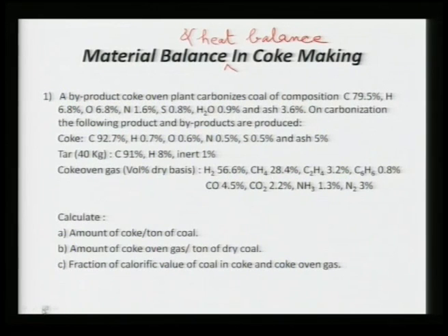The coke oven gas, you see the composition of the coke oven gas. If you look very seriously over here, you will find that hydrogen and methane are in the main proportion, around 56%, 0.6 and 28 point some percent. Hydrogen and methane are highly combustible components, and if used properly you can generate a large amount of energy from the coke oven gas which is coming out of the byproduct coke oven. Now, you should also see that this amount is what you will be producing on a per day basis, because you will be using around 10,000 tons of coke or more than that. So, that much amount of coal will be used and that much amount of coke oven gas will be produced.